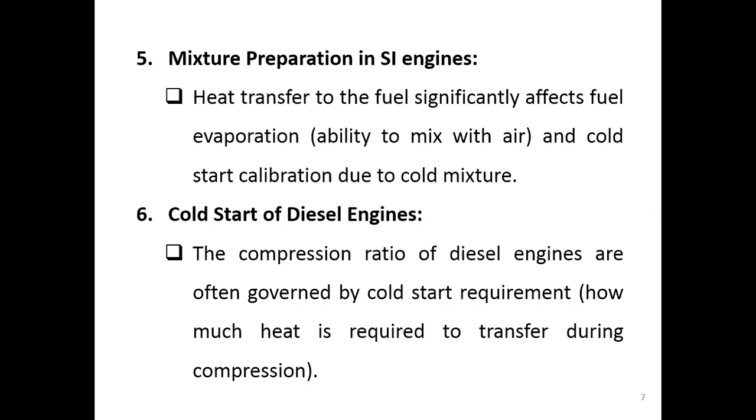That means if we have heat transfer going out from the mixture, especially during the winter seasons where the outside temperature is lower, our mixture falls in and loses its heat to the surroundings, because the surrounding temperature is lower. So this cold mixture, when it falls into the cylinder, is going to affect the start of the engine.